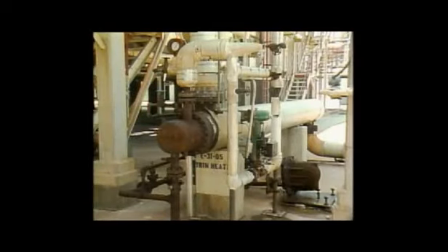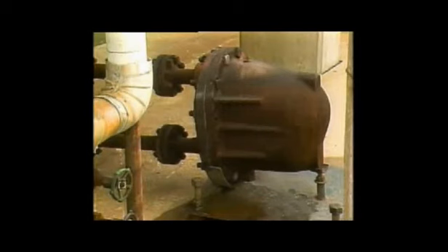On heat exchangers that use steam, an auxiliary device called a steam trap is often used. The steam trap drains water or condensate from the steam in the heat exchanger without letting the steam escape. Lost steam reduces the efficiency of the heat exchanger.